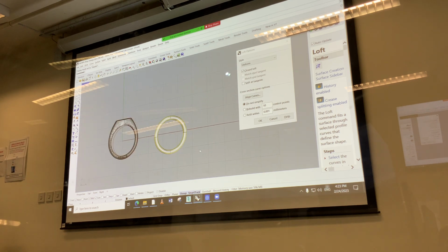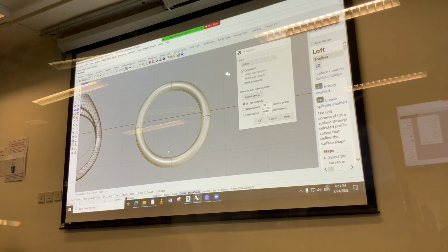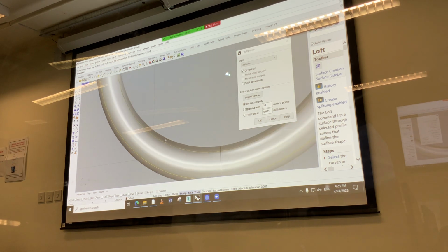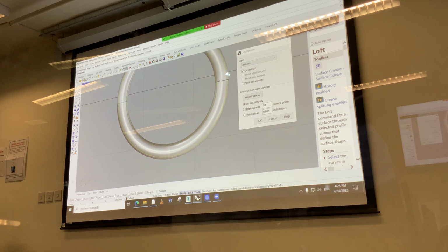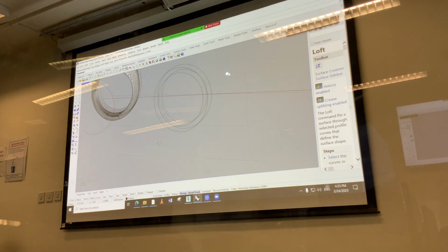So, with this one, I would obviously make the ring smaller. So if I go to front view here, you see that this is my line of the 18 millimeters. So doing this command would cut my ring here a bit. So that's maybe wanted or not wanted. So now I say cancel.